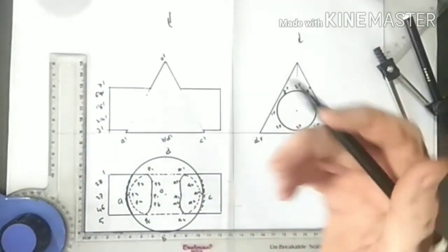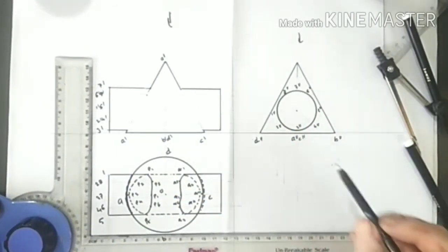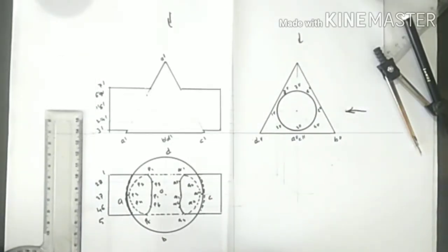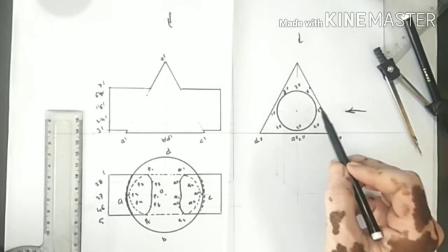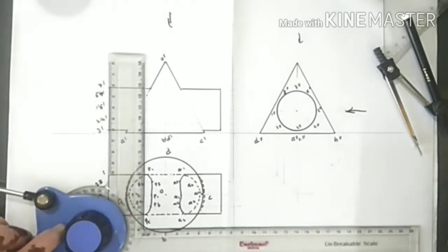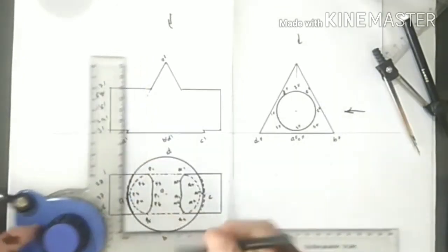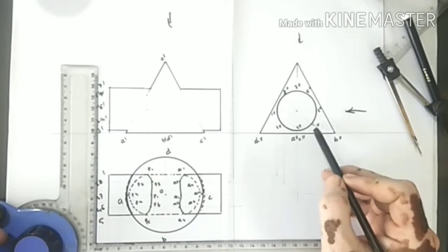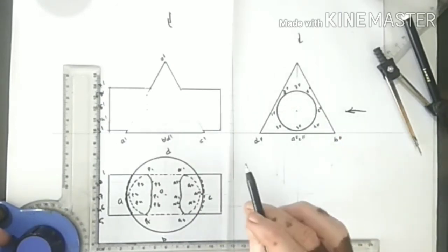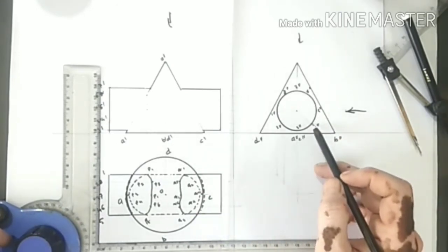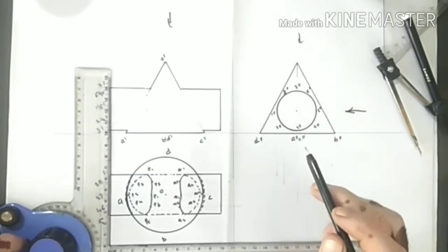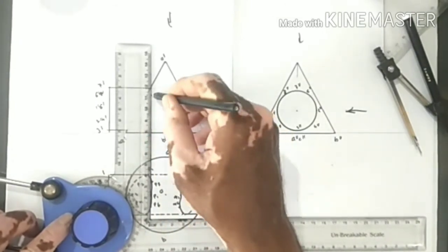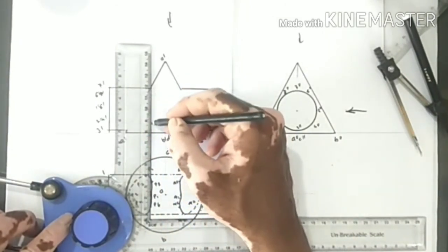Okay. Now the front intersection curve. So again you are seeing from this side and this side. So we will start from the 5. So 5. Project this 5. This 5. Okay, then 5 will join to 4, 5 will join to 6. If you are doing the left hand side, so P5 will join to P4, P5 will join to P6. So P5 and P6. So this 6 and this P4.